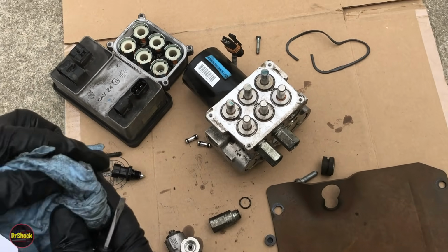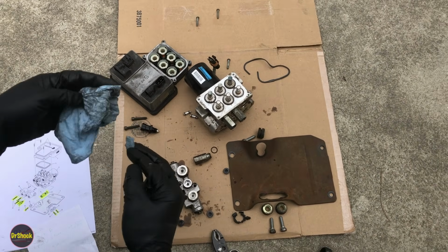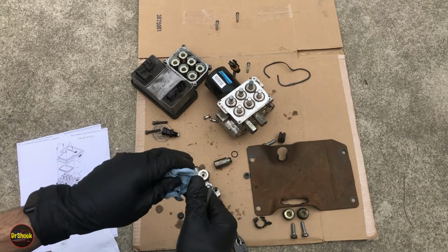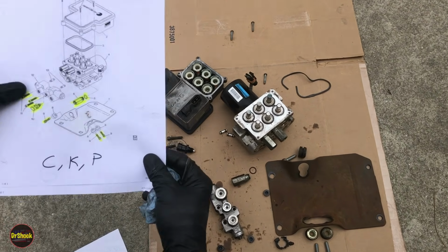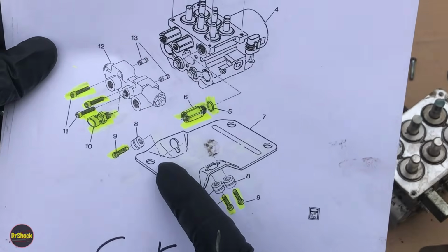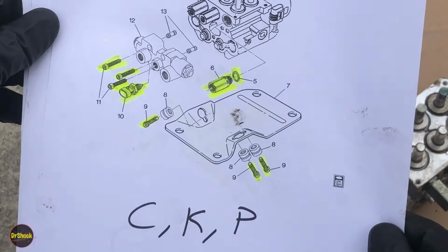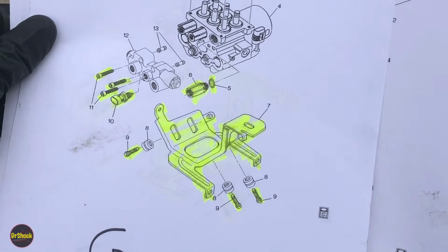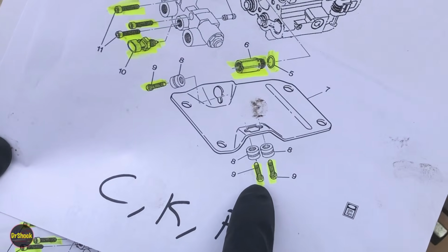Again, I'll put the part numbers for the CK trucks. I'm not going to list all these other vehicles because this video is really particular to C and K, but I thought I'd share that information because as you can see in the video, some things are common. If you've got a P-Van and you need a mounting bracket, you can take it off any CK truck. They all use the same brackets, all three of these. All of the G-Vans use the same bracket. All these trucks use the same bushings and the same mounting bolts.